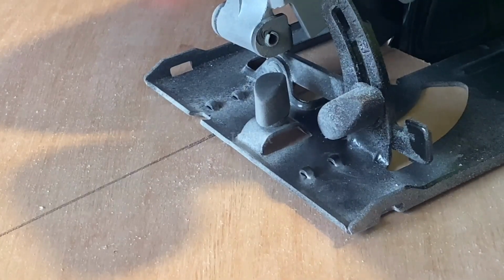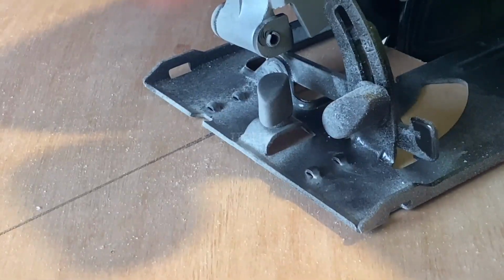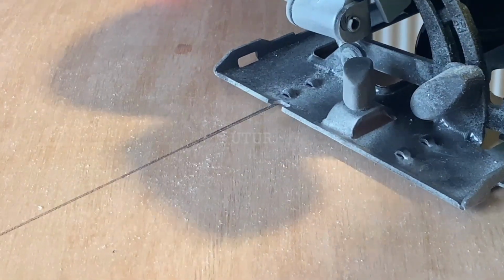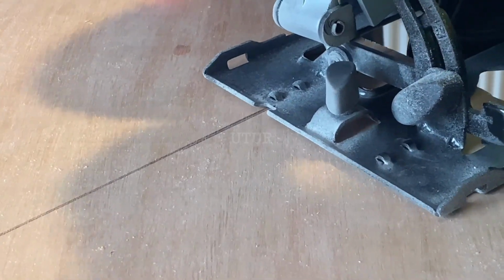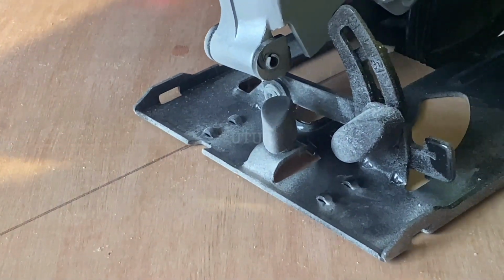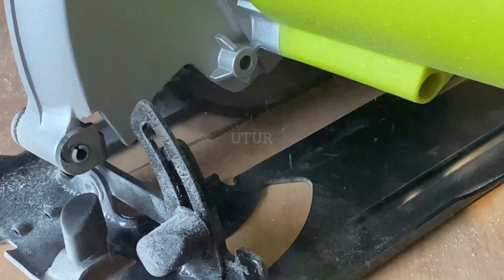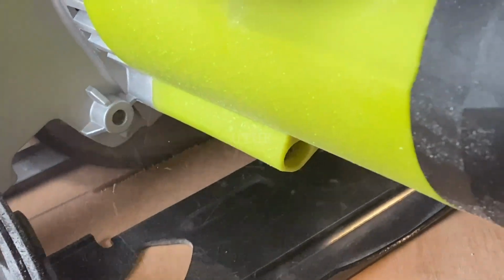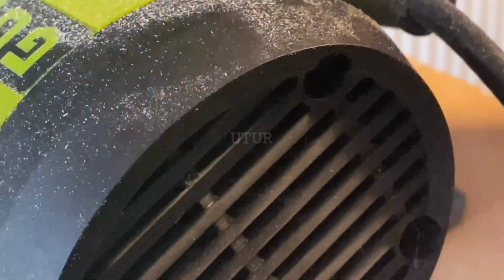And one more thing, whilst cutting through the wood linearly, if you stop halfway because you need to adjust your position, make sure that you do not take the circular saw from its line of travel or from the cutting path. Just switch off the working tool, and when you're ready to continue, just proceed from where you left off. Also try to make sure that the blade is free spinning and it's not catching onto the wood before you proceed. As previously highlighted in the video, if it catches onto the wood before it moves on, then you might experience binding or kickback.